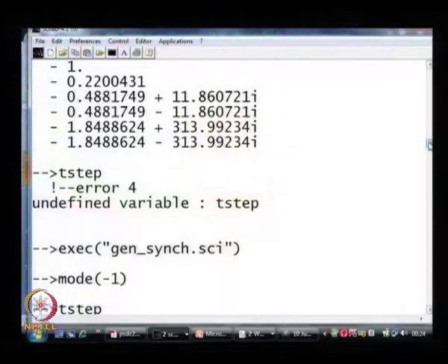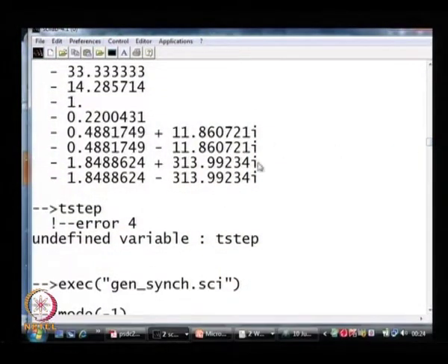Okay. So, although the system is stable, remember all the eigenvalues for a particular operating point have negative real parts. So, it is a stable system, but simulating it may result in problems if you are using methods like Euler method. So, that is the summary of what we have been discussing so far.